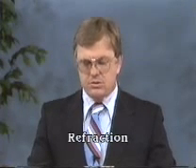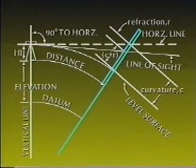Another correction that must be considered along with curvature is refraction. When light passes through the atmosphere, it bends slightly, causing an object to appear higher than its actual location. Again, in the illustration, we can see the actual line of sight is lower than the horizontal line by the difference labeled R. This difference is a refraction correction.